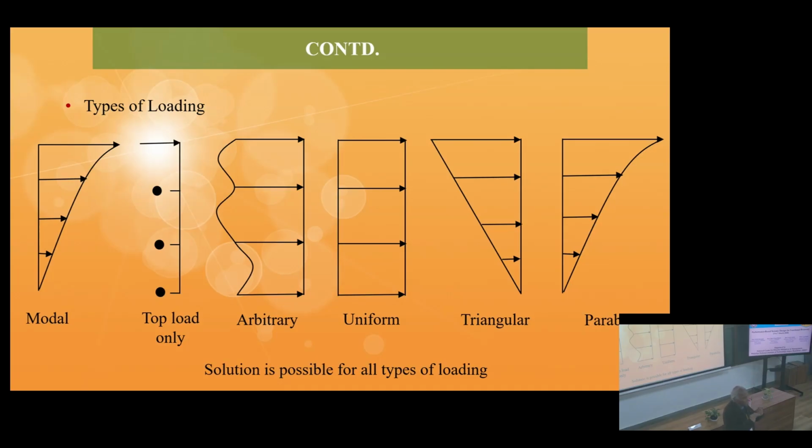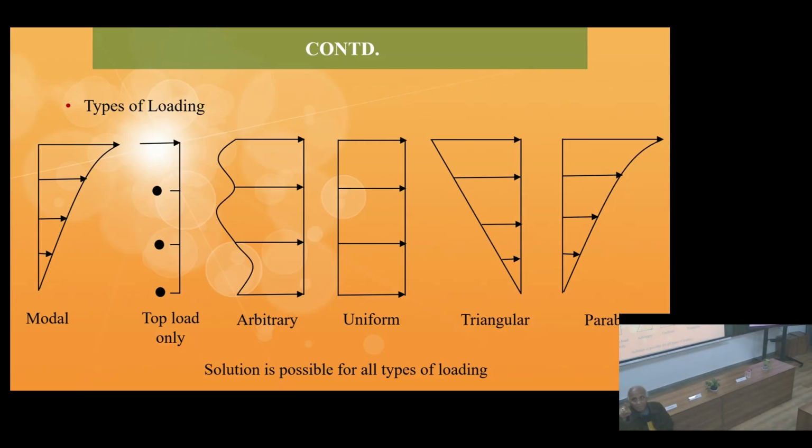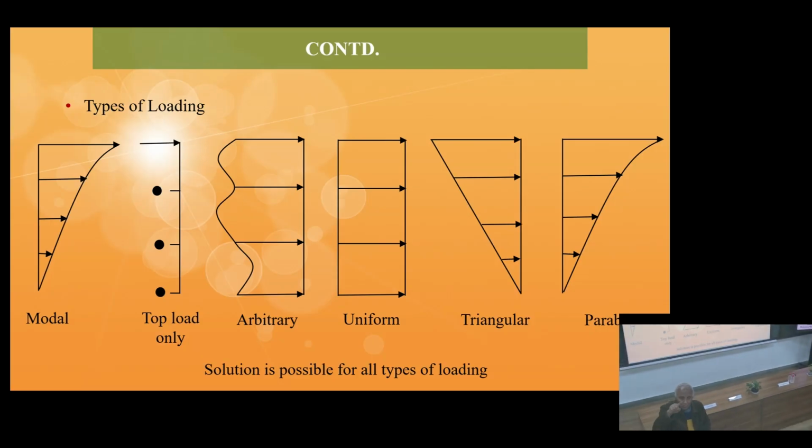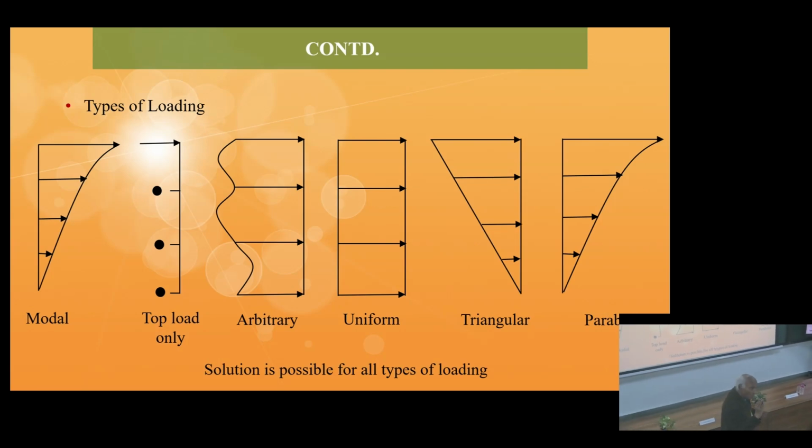So the next thing we are saying is that the load distribution is such that it follows the mode shape. That means if here it is P1 and then here it is P4, P1 to P4 will have a relationship, and that relationship will follow the first mode shape, a curve.